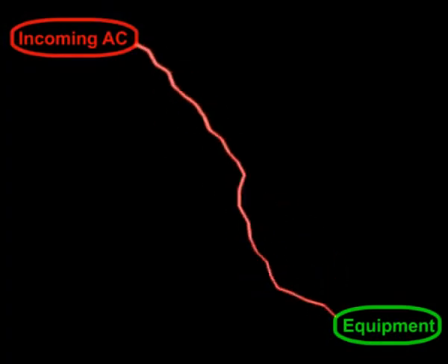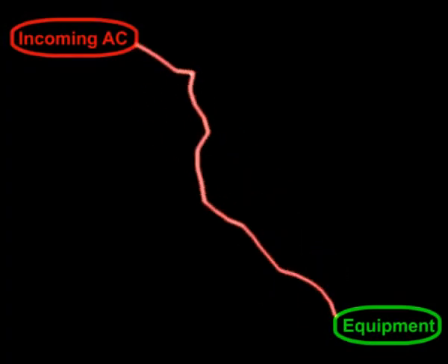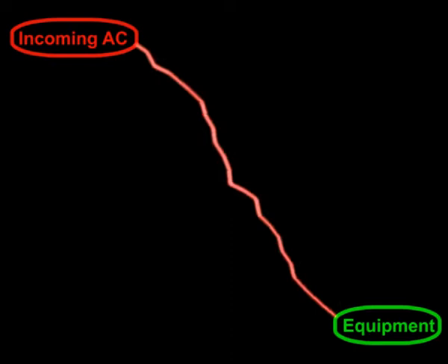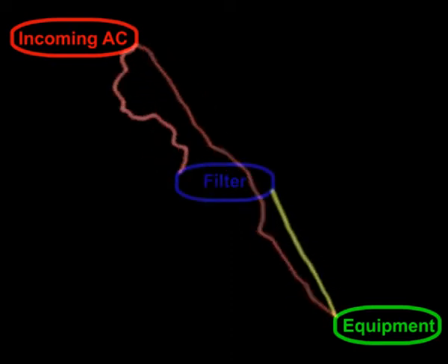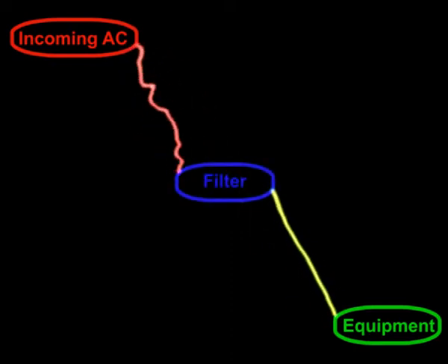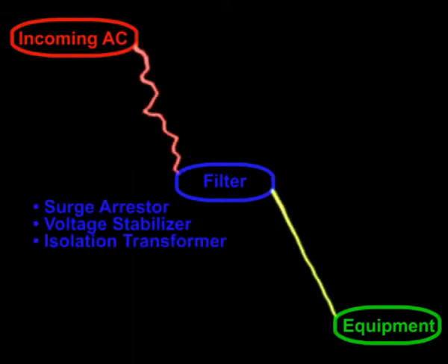The telecom equipment needs to be supplied with a steady voltage without any disturbances. If the AC is of poor quality, it needs to be filtered before it enters the rectifier. If not, there's a risk the rectifiers will break down. This filtering step requires AC filters.